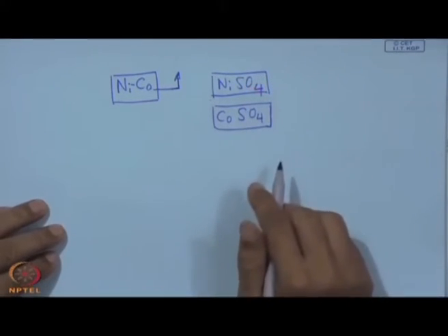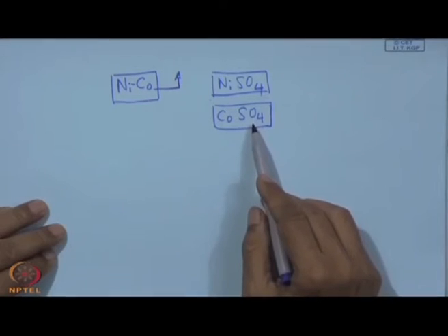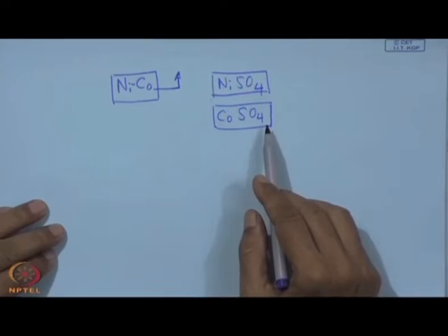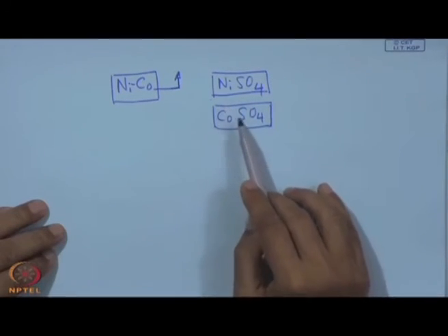So, wherever we find a combination that will be useful, and when they are really compatible, then this co-electro deposition is also possible. In that case, definitely the current density, the voltage across the electrode, and the temperature are the few things that will affect the deposition rate or the composition.